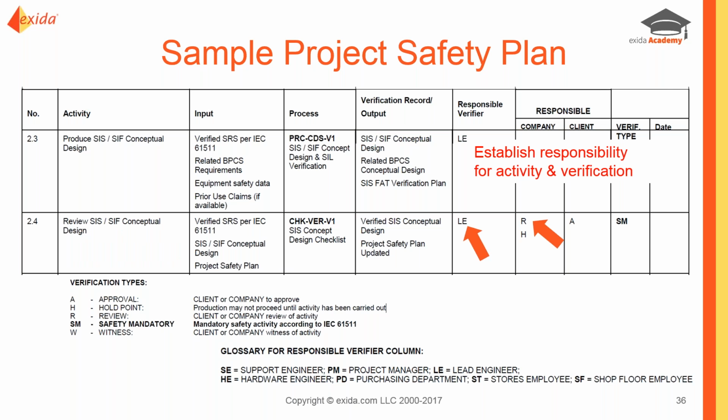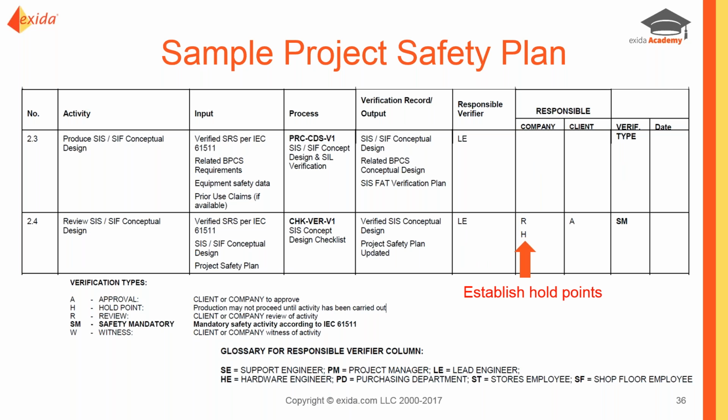And then we define who is responsible for the activity and who is responsible for the verification. And of course the key is down, the glossary's down at the bottom, on these responsibilities can be adjusted and tailored to suit what your individual organization or individual project requires. We also establish these hold points. What is safety mandatory that must be done as part of the standard? In this case, the SIF conceptual design, this is where one of the stage FSAs is required. So we've indicated that hold point, and then it's a safety mandated hold point.